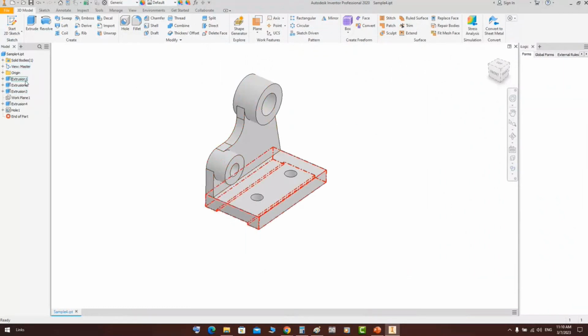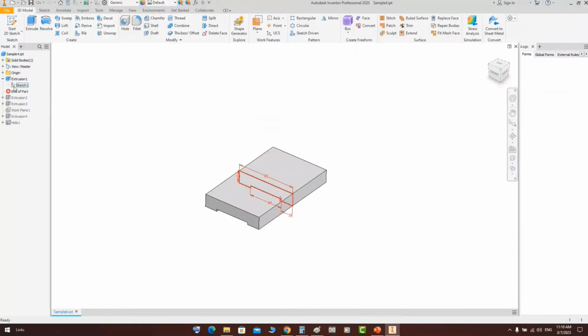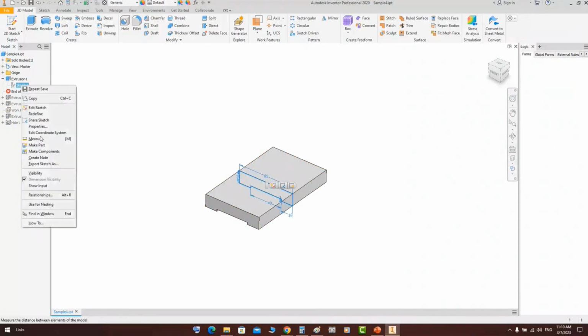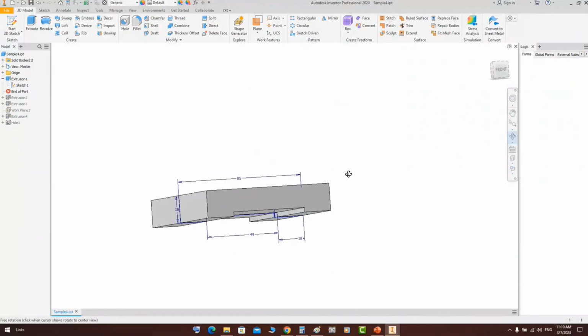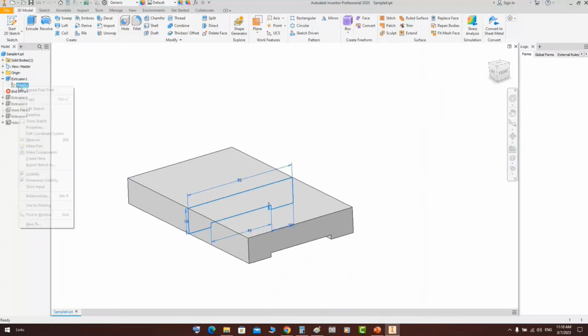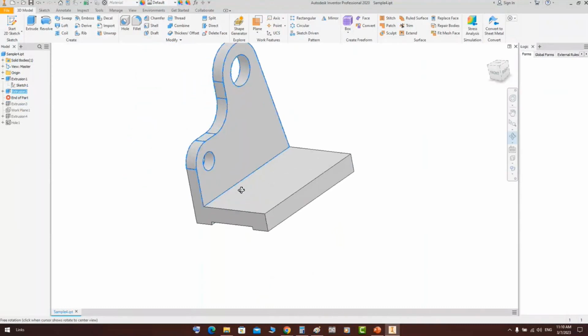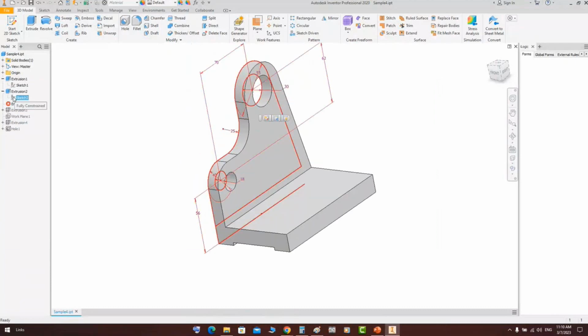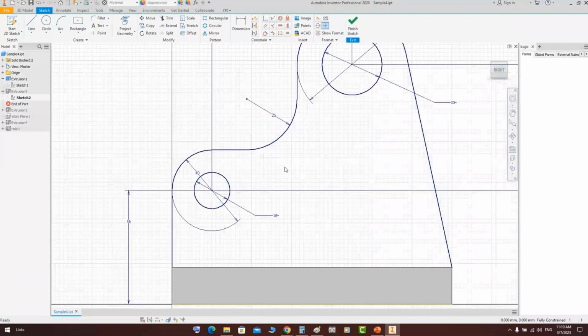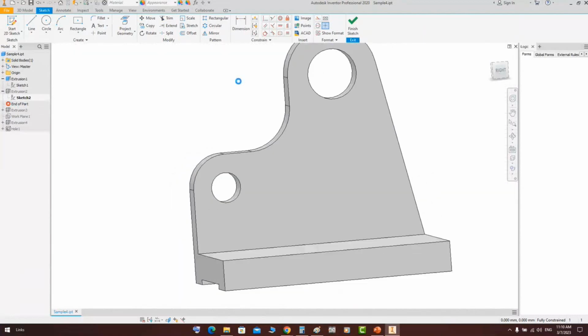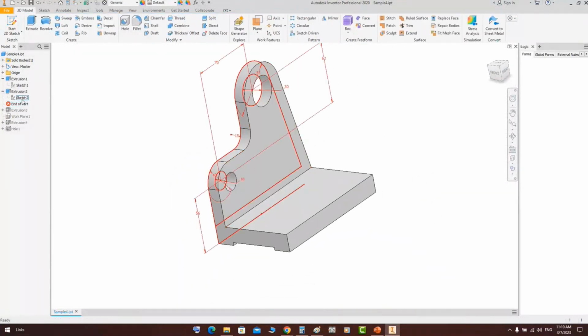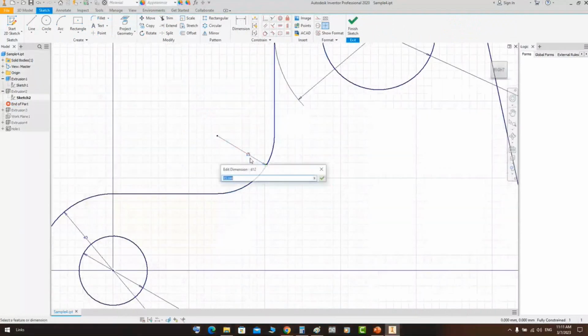And you can figure that, as mentioned, the feature that created this part. So if you move the end part after the first feature, you can figure that we have this sketch. We used it to generate this feature, make it invisible. Now for the second feature, we make this one by using this sketch. So anytime if you would like to change the sketch, when you come here and make a modification, for example, change this one to 15. Okay, so when you click finish, the 3D model will change based on the change in your sketch.